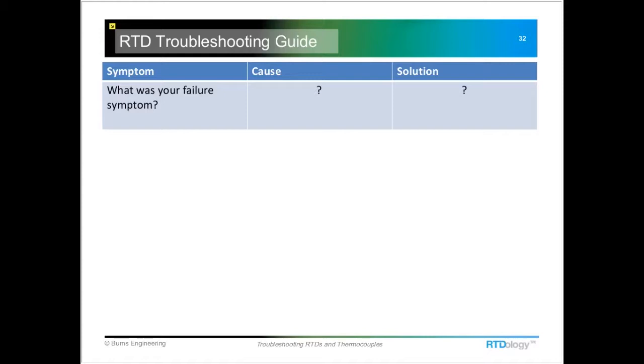I think, Bill, if you look at the last question there, there's probably a little more detail. Okay, so the hot junction was 2 feet long, and the probe was inserted into a hot environment. Would it be measuring the terminal end or the closest junction to the meter? It'd be the closest junction to the meter. Like I said earlier, if you were to have another accidental junction outside of your process, it's going to be measuring it there. So whatever's closest is the way that's going to work. And I believe that's the right answer for that.